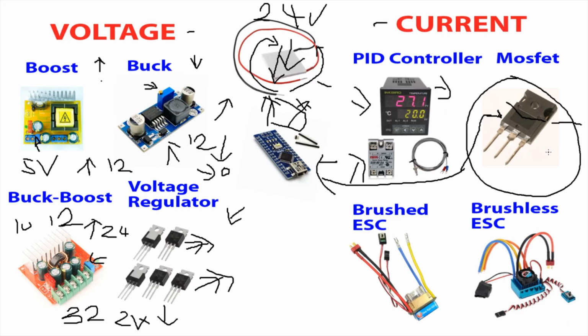It is normal for them to need way more voltage, say 12 volts or more, to fully open this switch. If you buy some random one and power it with 5 volt, it will open the gate, so you'll think it's working. However, it will only open this gate a small amount, and that can result in significant heating. The rest can be lost as heat, and boom.